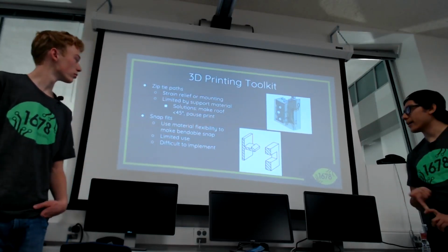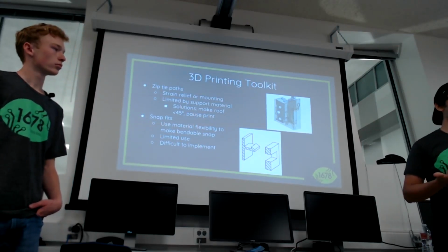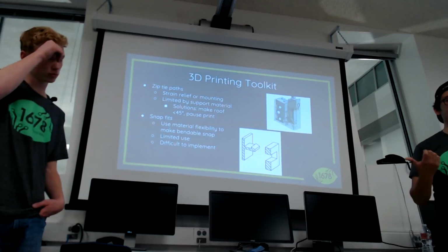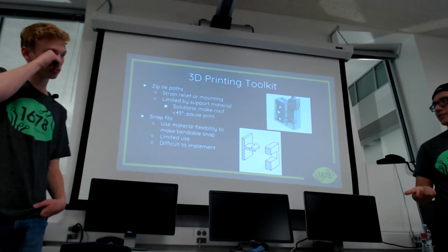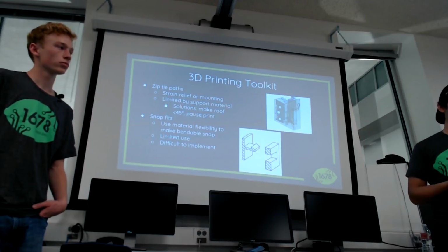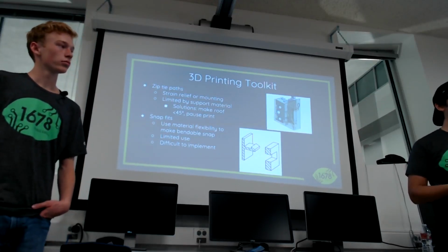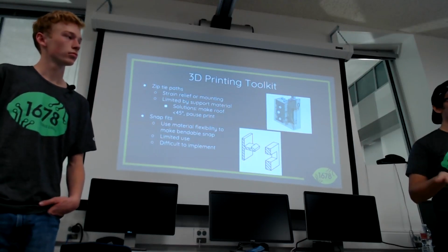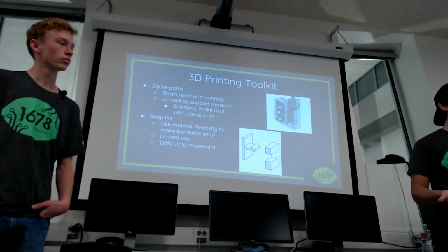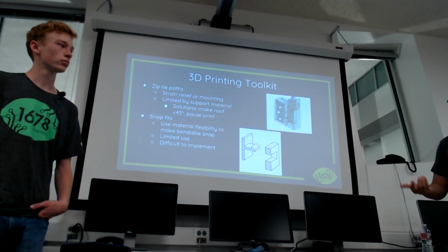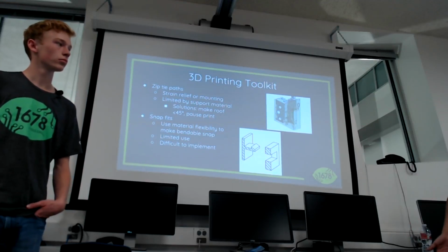In addition to that, modeling them is a fairly difficult stress analysis problem, because normally you have a different length and you have different materials, and the 3D printed materials don't always exactly line up with the known textbook values of the plastic. So you kind of have to play around with them before you get them correct.